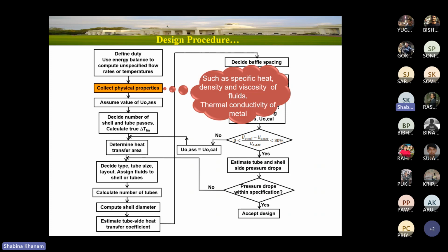So you get the unknown temperature of the other fluid. Now you will have both the inlet and outlet temperatures of the second fluid. Now you calculate the average temperature of that fluid. At that average temperature, you look up the specific heat value from the chart. That specific heat value should be equal to the assumed value. If it is so, it is fine.